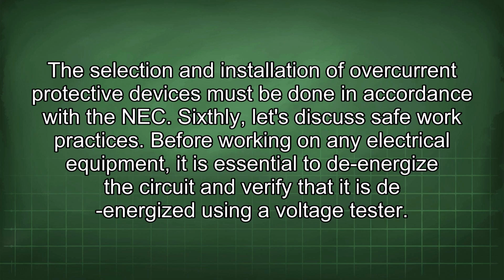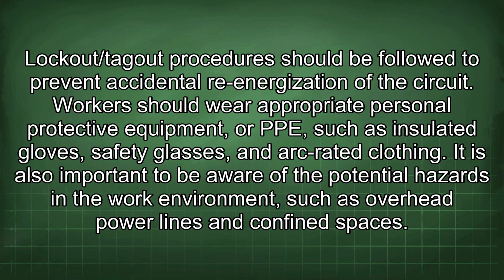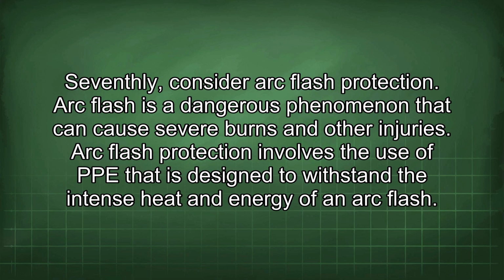Sixthly, let's discuss safe work practices. Before working on any electrical equipment, it is essential to de-energize the circuit and verify that it is de-energized using a voltage tester. Lockout/tagout procedures should be followed to prevent accidental re-energization of the circuit. Workers should wear appropriate personal protective equipment, or PPE, such as insulated gloves, safety glasses, and arc-rated clothing. It is also important to be aware of the potential hazards in the work environment, such as overhead power lines and confined spaces.